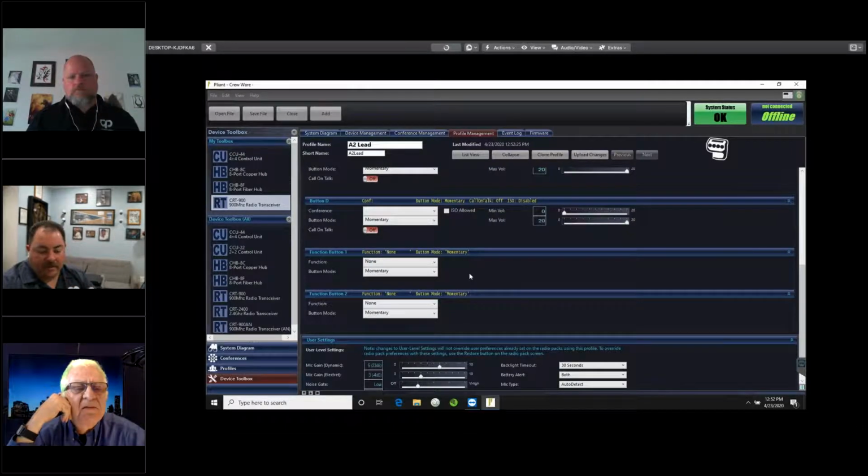Because you'd be coming in on one. So the aux doesn't automatically mix minus the in from the out? I don't believe so. So it's not really a 4-wire in. Right, because they can be split. You can use them for 2 different things. Like an aux in could be a program. You could put program in on a 2-wire, or you could put program in on a 4-wire channel, however you were designing your system, whatever was best for you. And then your aux out could be used for a second SA. So they are 2 split things, and that's a 1/4-inch jack on the back of the CU.